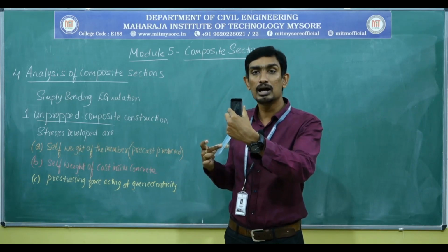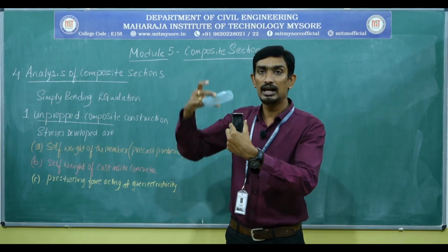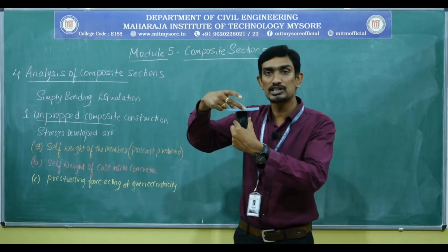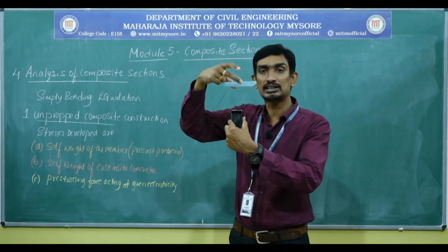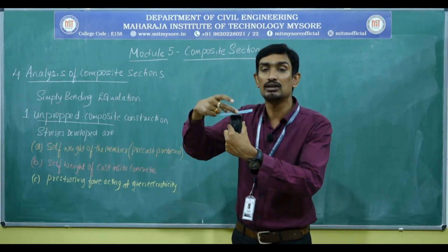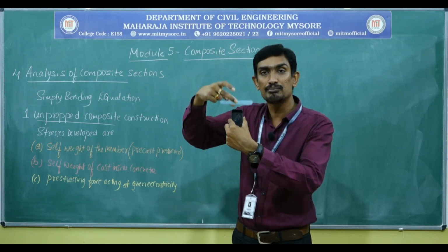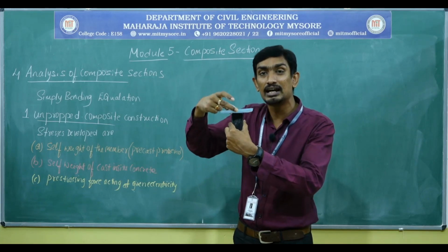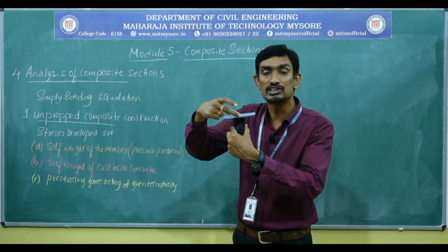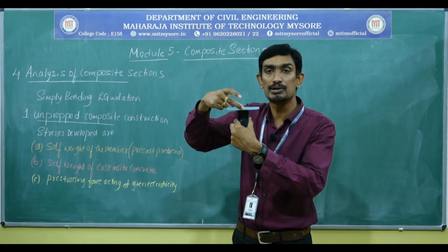At that particular instance, the self weight of this member will also be considered while analyzing the composite section under the unpropped construction case, because it will also come into the picture.